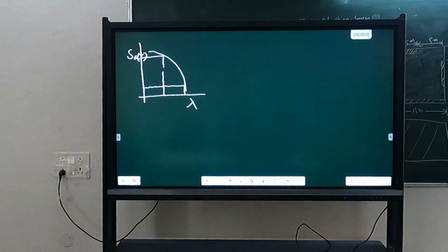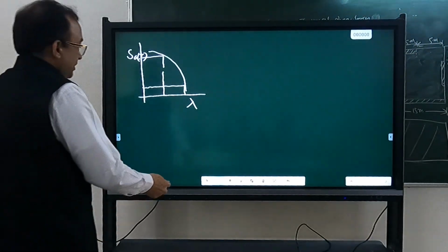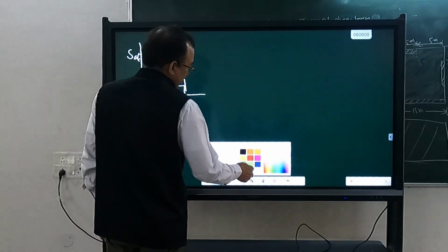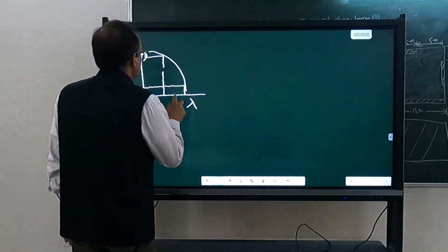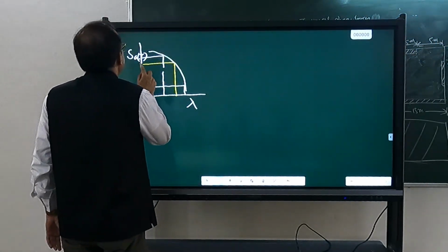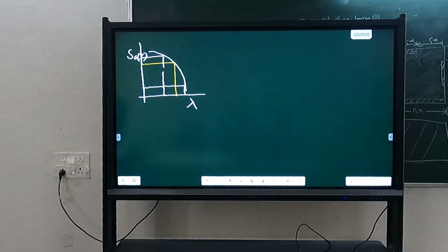So it is only giving you the probability distribution of occurrence of different levels of spectral acceleration at your site. Now you decide for what probability you want to design. Then for that probability of occurrence, you can read the value of SA which you should consider in your design.